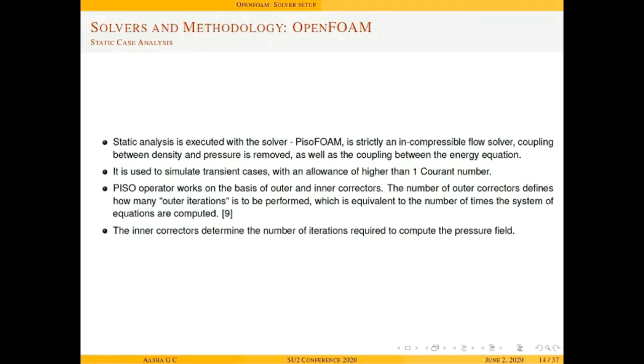And so pimpleFoam works on the basis of outer and inner correctors, where the number of outer correctors defines the outer iterations performed. This is like saying the number of times the system of equations in the form of a matrix is computed, irrespective of the convergence of the solution, at least for static use. And the inner correctors determine the number of iterations required to compute the pressure field,